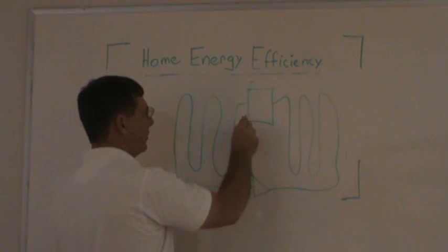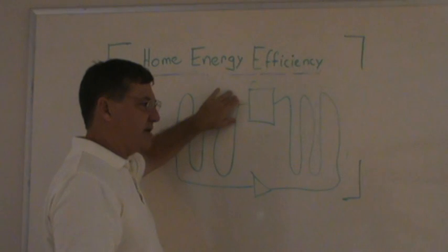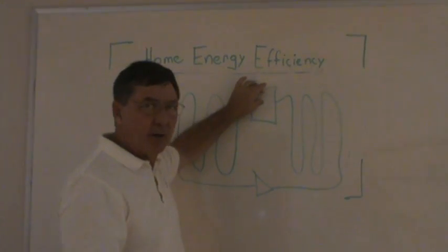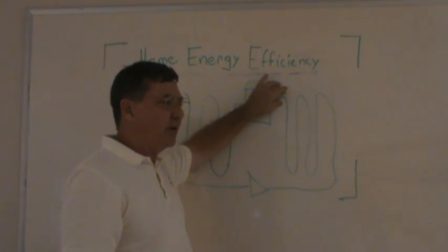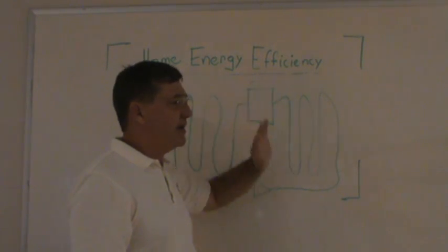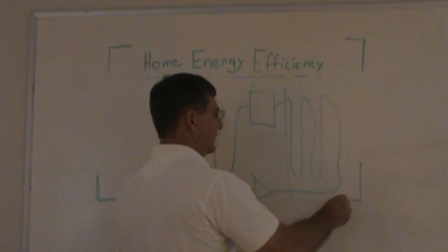The compressor pulls the refrigerant when it's a vapor, it's hot, it compresses it, and when it compresses it, it wants to change state again to go from a vapor to a liquid, and when it does that, it drops its heat. So this would be the outside unit.